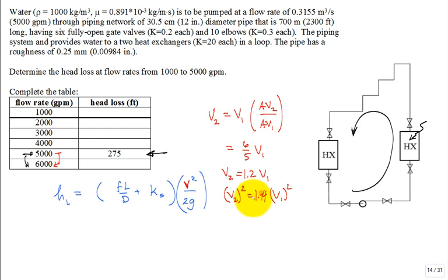So what would the head loss do? Well, the friction factor may change, 0.019, maybe it goes 0.0191, 0.0192 or something. It's not going to change significantly, right?